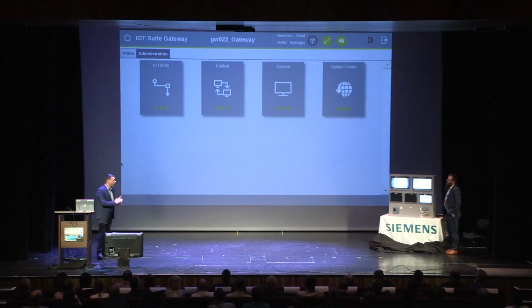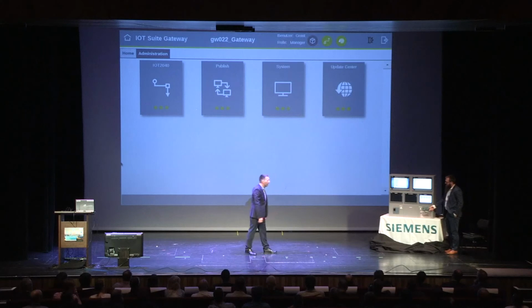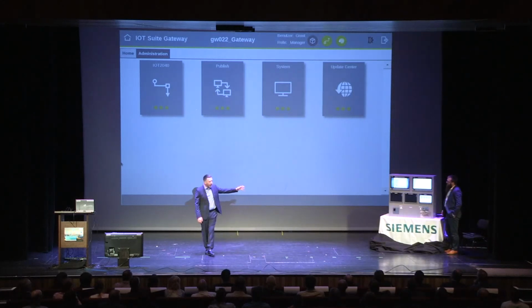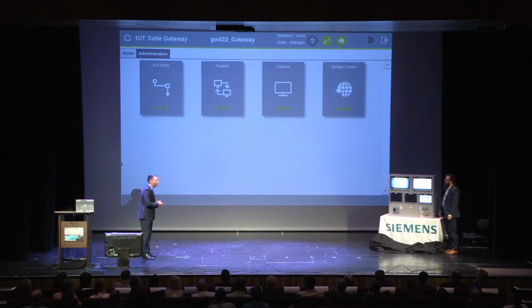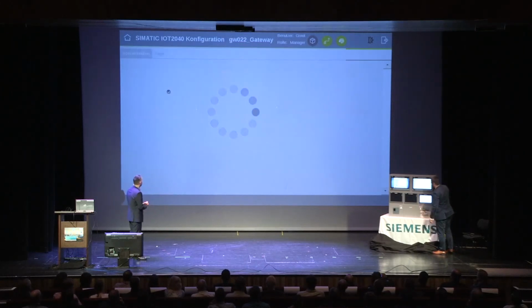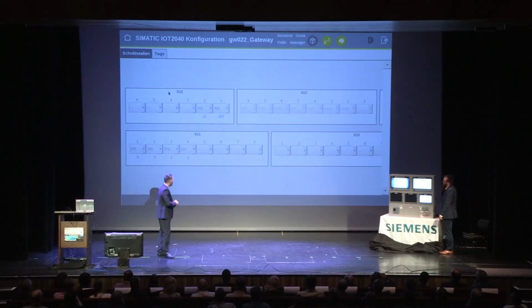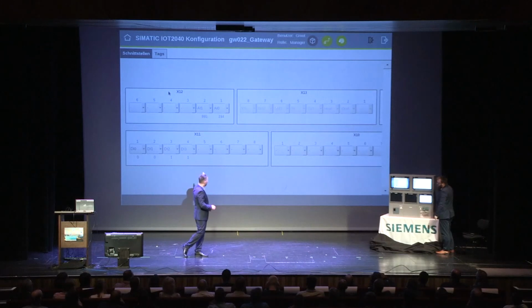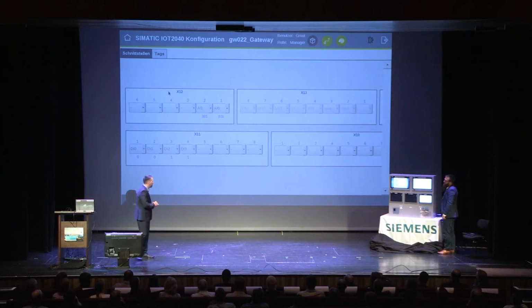So we start at the smallest device, the gateway, at this one. The first scenario we want to show you: we already wired our simulator to the IoT box, but we would like to show you how to configure the data input for this box. So please open up the IoT box app. In here you can see all the data, and an electrician can see, if you choose the entries, if the values are received and correct, or if the wiring he made is working correctly.